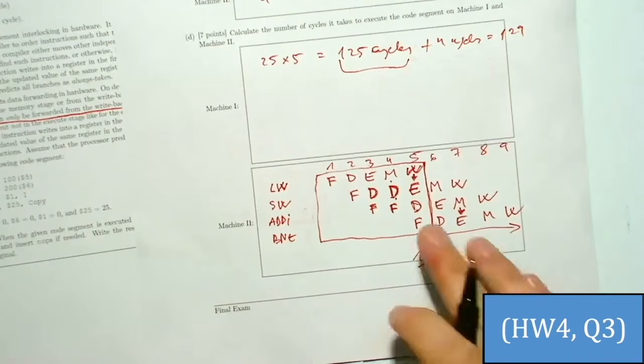Yes. Something that is not really clear, that's also been an issue in another homework, is that to me the effectiveness of the forwarding is dependent on the dependency checking method. If you use scoreboarding, right, then you do bypassing from the memory stage to the execute stage.